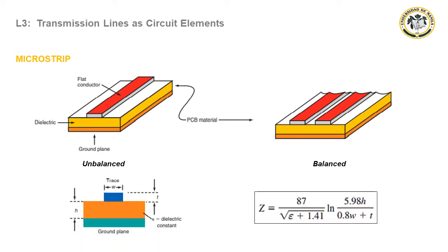The characteristic impedance of microstrip, as with any transmission line, is dependent on its physical characteristics. It can be calculated by using the formula shown. The dielectric constant of popular FR4 fiberglass PC board material is 4.5, while the value of dielectric for Teflon is 3.